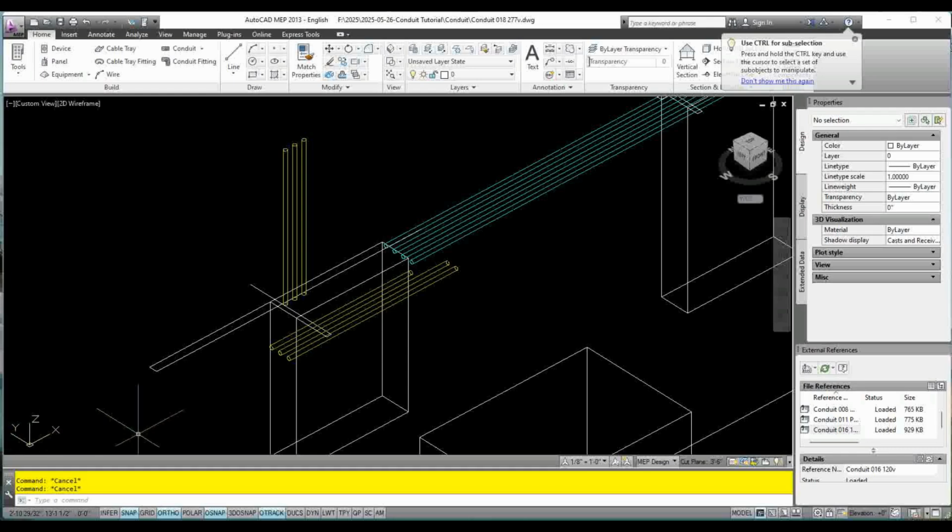We got to rotate this UCS. So type in UCS, hit enter. Now we're going to rotate what? We want to rotate Y to Z. Well, in order to do that, X is our pivot point. So type in X, hit enter. Okay, now drag this thing around. And yeah, there we go. Right, that looks about right. Y is where Z was. Click once on the screen, escape, escape, escape, right?